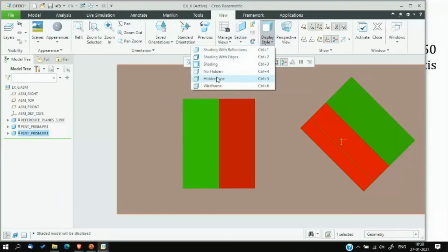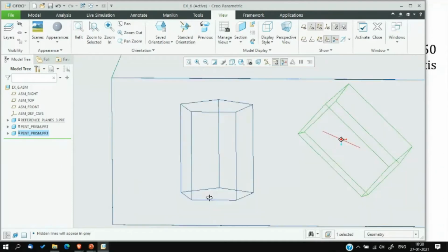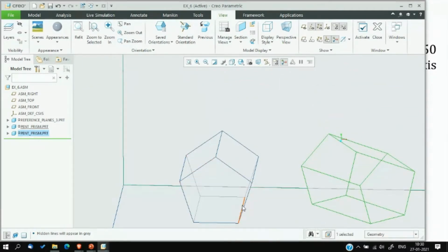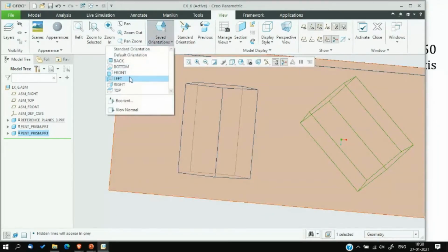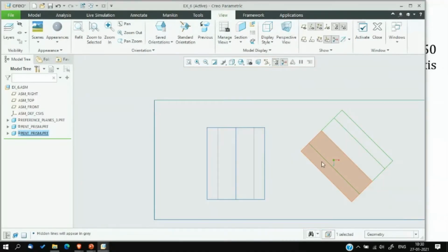See, like this. This is the first initial front view. In the initial front view, these two inner lines are hidden lines because they are below our actual object. See these two lines, they are hidden lines. And those two lines will be hidden in this position also. In this position also, this line as well as this line will be hidden because this figure is rotated to draw this. So both these two lines will be hidden lines.